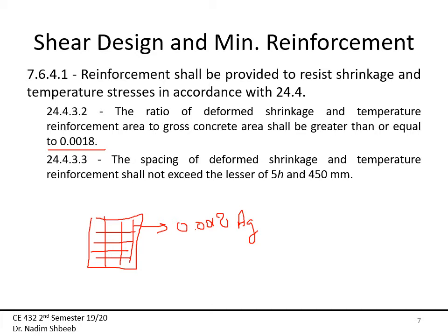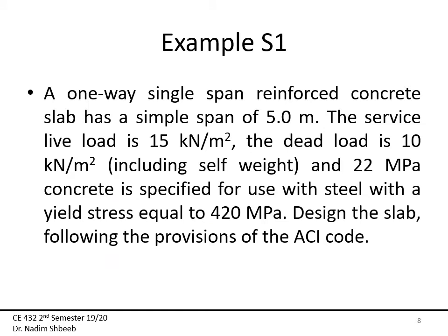Now we also have to keep the spacing between that, and this is the spacing that we are talking about. So the spacing shall not exceed the lesser of 5H and 450 millimeters. Okay, so we need to keep that in our minds when we do design for slabs. With that, I'm going to start off with an example right away.